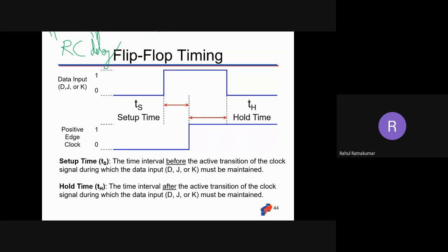Clock activation, the positive rising edge of the clock or the negative edge of the clock, is when our process has to start. So before starting the process, all my internal capacitance, all the time delay or non-linearities within your modules or gates has to be addressed. So the minimum time before the clock comes, my input has to be ready.